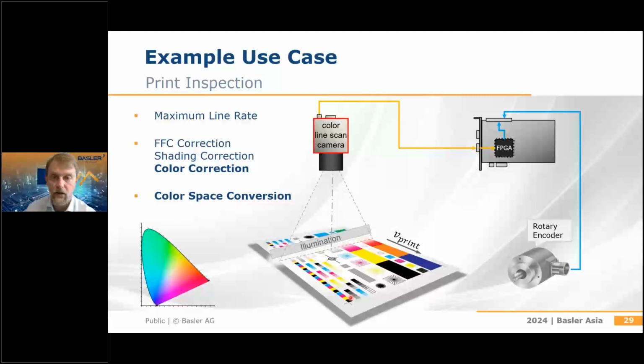This is now about structured light. It's a little bit more complicated. It's a mechanism where you have a kind of projector that is projecting a gray code on top of your material. Here below you see a real world application with a very white image, then a black image. This is for getting a local adaptive thresholding that is making the system very robust. And then it's going through a pattern that is increasing its frequency from step to step. It's very similar to a binary code.